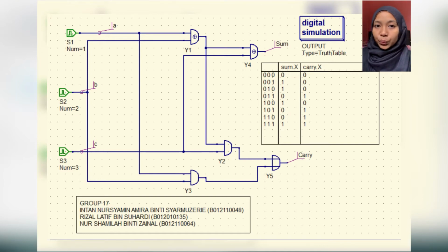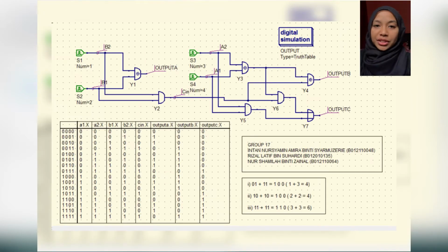From the truth table, we can obtain the Boolean expression for both the sum and carry outputs. Using those expressions, we can build the logic circuits for full adder, but by simplifying the equations further, we can arrive at a point that a full adder can be easily implemented using 2 half adders and an OR gate. Addition and subtraction are 2 basic arithmetic operations that must be performed by any digital computer. If both these operations can be properly implemented, then multiplication and division tasks become easy.